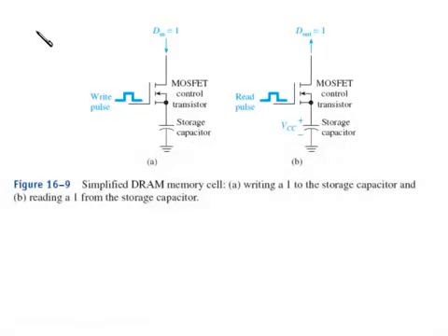So the main difference that dynamic RAMs have over the static RAMs is that their main memory is charge placed on a storage capacitor. What I'm showing in this diagram is, after the address decoding is taken care of, let's say we're trying to put a 1 into a storage location, in other words put it on a storage capacitor. You would place a 1 at the D N line, which was decoded to this point, and then provide a write pulse.